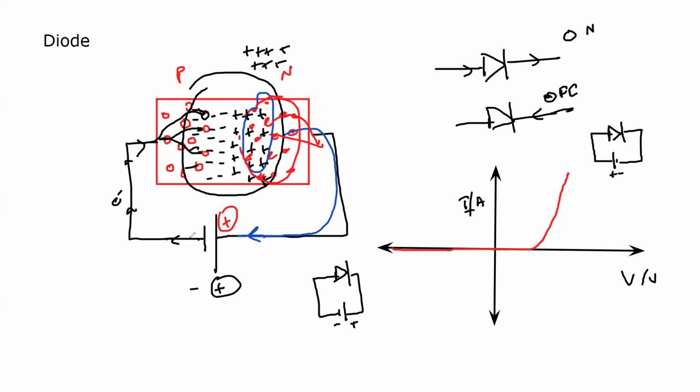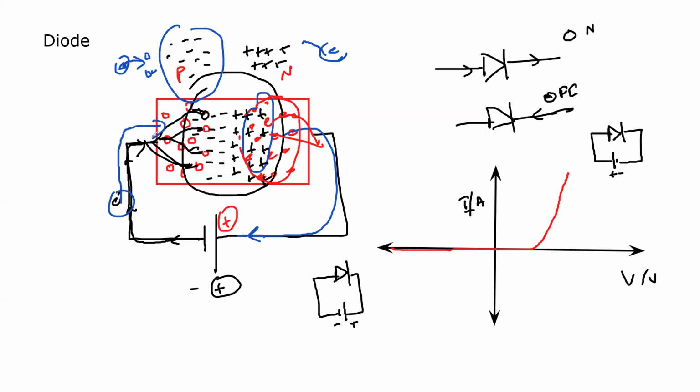And the same thing: when electrons are connected to a p type, these electrons combine with the holes. When they combine with the holes, the overall negative charge on the other side is increasing. So actually what happened is that here we have holes and here we have electrons, but there is no movement. Why is there no movement? Why are they not able to move? Because of mostly negative charge. Like charges repel each other. So because of the repulsion, the electrons are not able to move across the barrier.